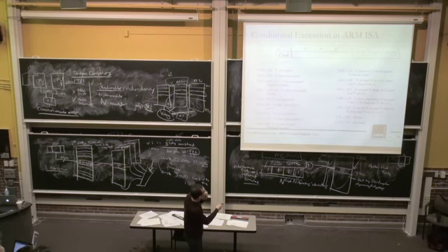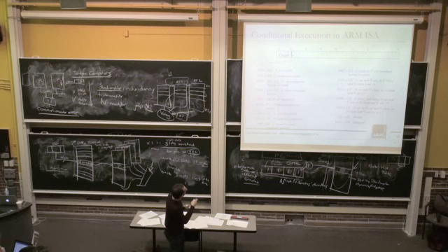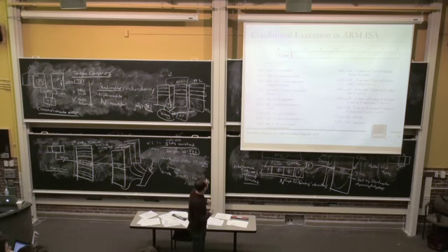Always. Well, if you want the instruction to be executed always, you'd better set those condition bits to 1110. That way the instruction is not dependent on a predicate, meaning condition register. So ARM has condition codes, so you need to check the condition code. For example, if the condition bits are 0000, this equal condition code is set, which is the Z condition code. If the Z condition code is set, then the instruction is executed. Otherwise, the instruction is not executed. Make sense? If you've seen ARM, it's pretty simple. It's one form of predicated execution.